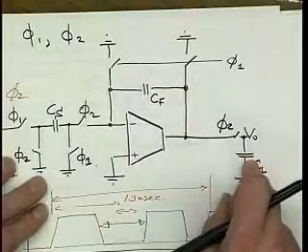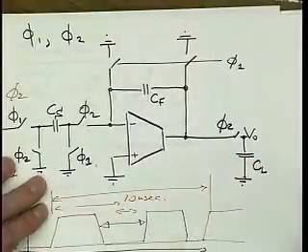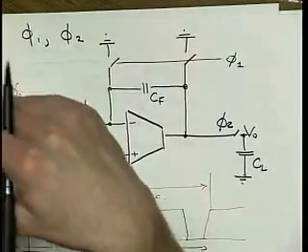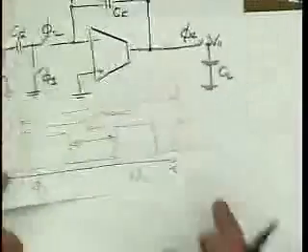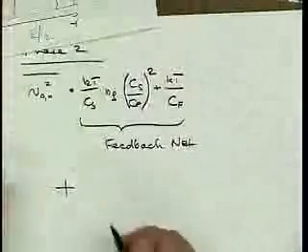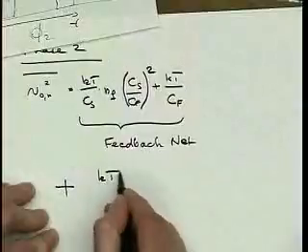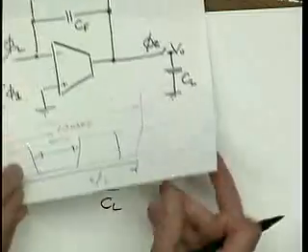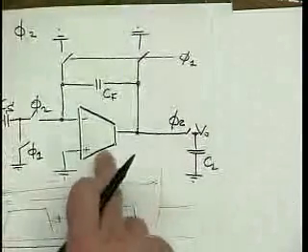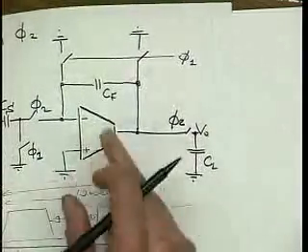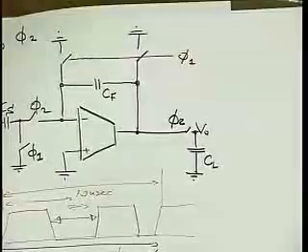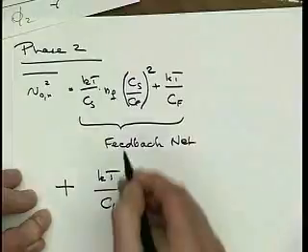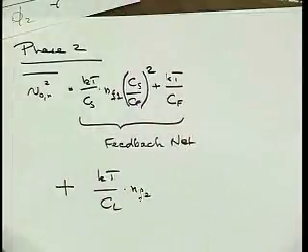Now we could calculate that with all these integrals and so on, no big deal, but that's kind of painful, and we've done it already, so we just try to remember what it is. First of all, the capacitor is CL, so we get a term that is kT on CL. Secondly, our amplifier here also will have a noise factor. Maybe it is that common source stage from the homework, and so we call it NF2, and NF1 for the other, just to make that clear.